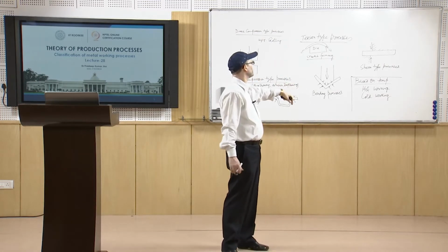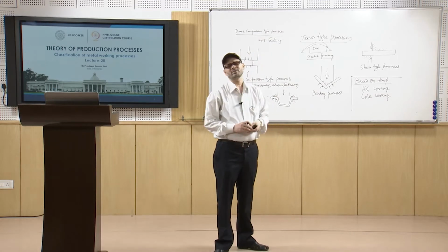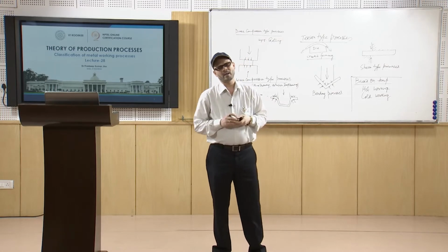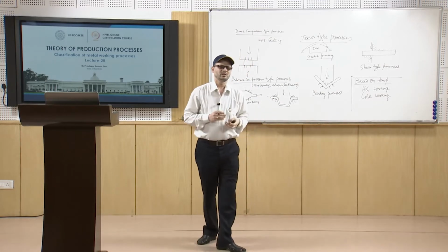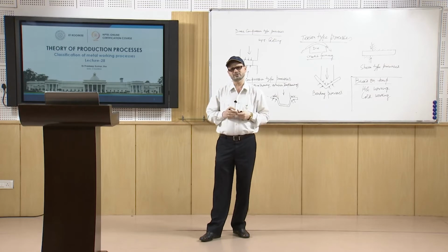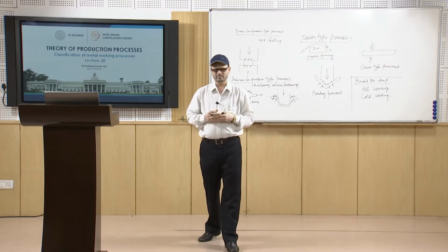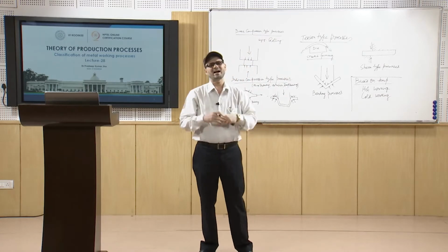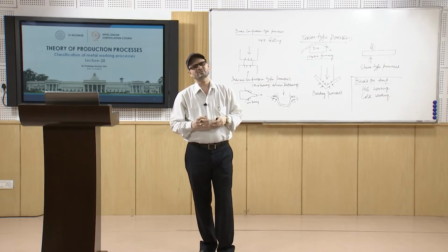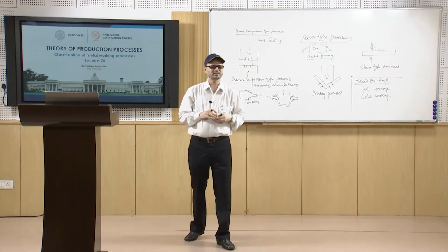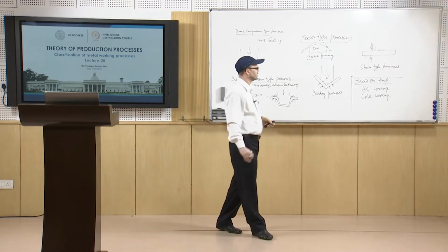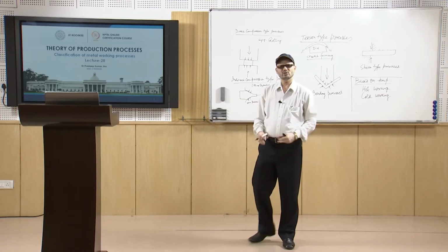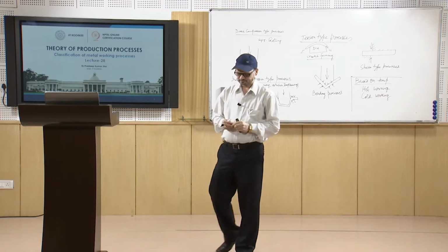But there are other aspects of hot working and cold working. In hot working, the challenge is to have a good surface finish. Because the working is done at a very high temperature, there is oxide formation at the surface, because at high temperature you have quite high reactivity. So you have the chances of oxide formation at the surface. But that problem is not there in the case of cold working. So this is how they are basically categorized.